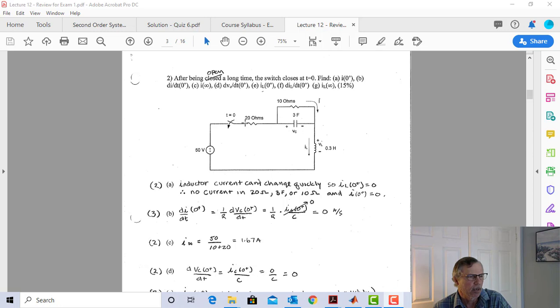So what do I know? I know that I have no current here, but you know, this side is not nailed down because it's open, so I think I'm going to start down here. The rules tell me that there's no voltage across the inductor, so I'm going to start at 0. I really should have a little ground symbol here. So I'll start at 0. I'm going to go up 0 because there's no voltage across the inductor.